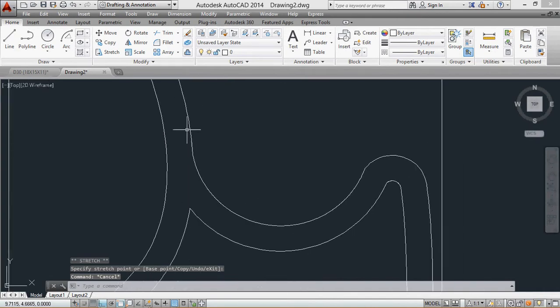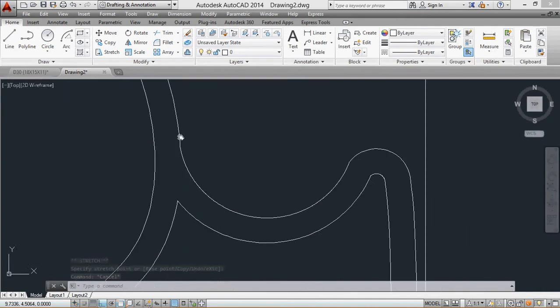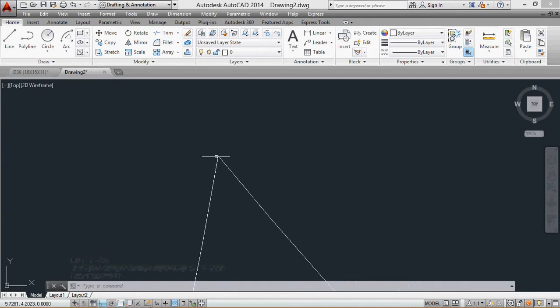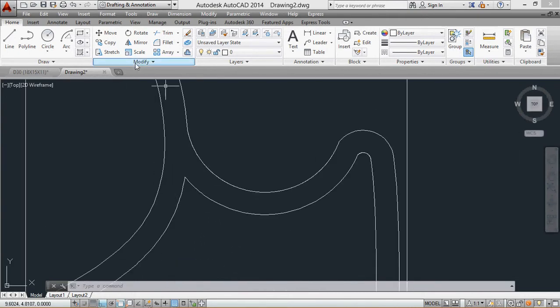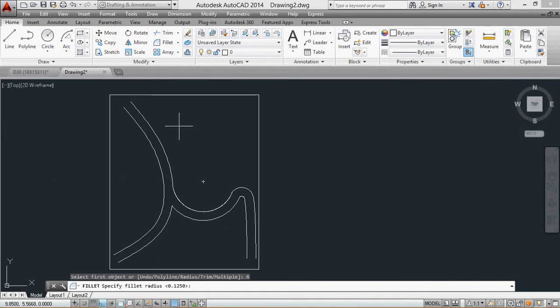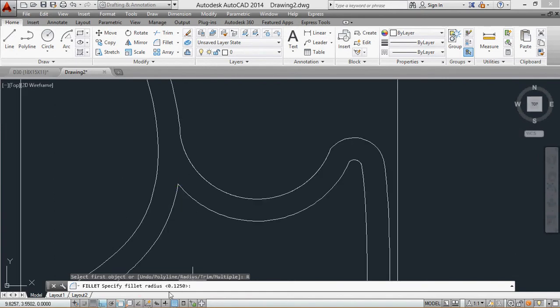material on the side. Now, another way of solving these little issues, maybe there's extra material here where one line is longer than the other, you can't see it, it's going to take you forever. What I recommend is using the fillet command. You can leave it, if you want the 90-degree angle, you can leave the radius at 0, but if you want a little curvature, which I recommend for even plastic molding or anything, do at least a fraction. I have 0.125, that might be a little bit too big, so I'm going to do half of that, which is 0.0625.